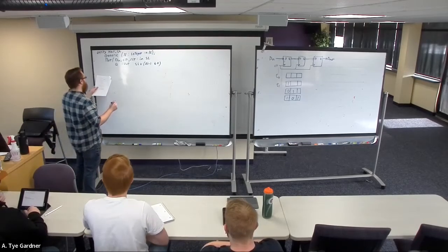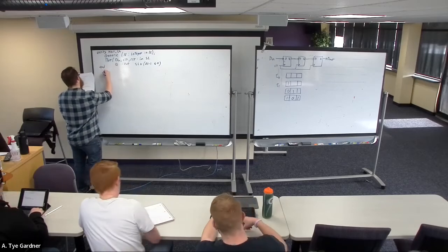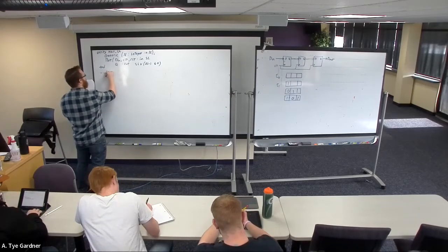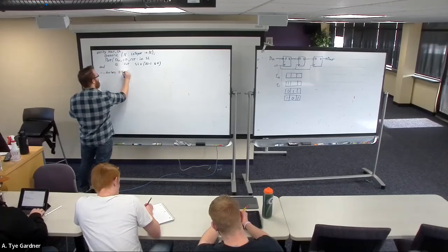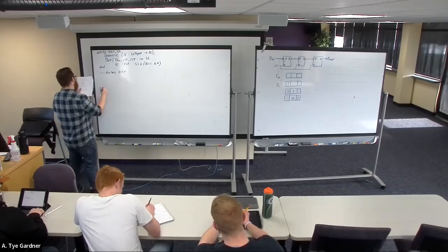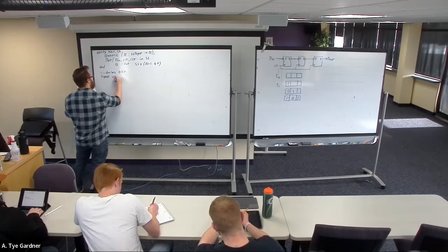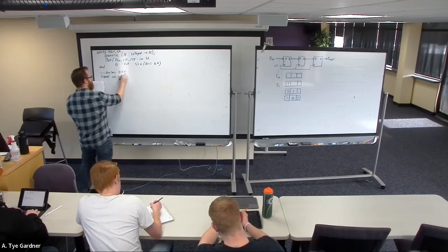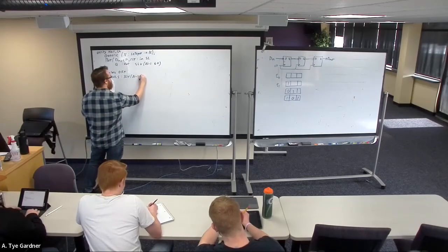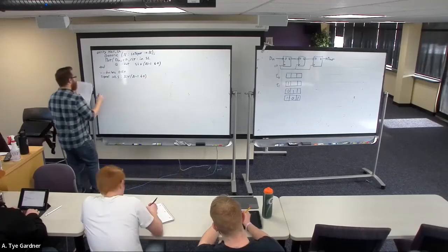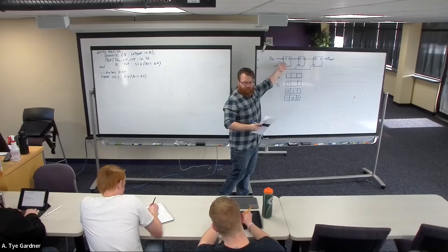And then here we'll have the end. Then I'm just going to put a comment that says declare D flip-flop. I don't want to write all the code for the declaration of the flip-flop. Then we're going to make a signal, and we're going to call it the internal signal. And it's going to be a standard logic vector of n-1 down to 0, right? Because what I'm building is this shift register.